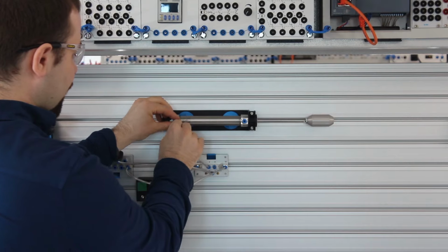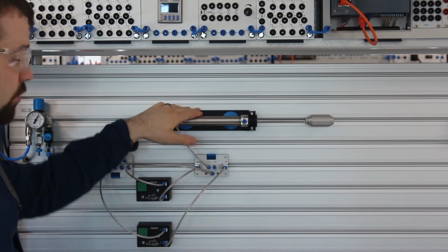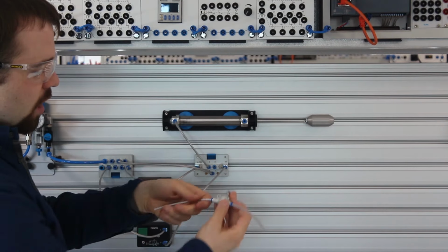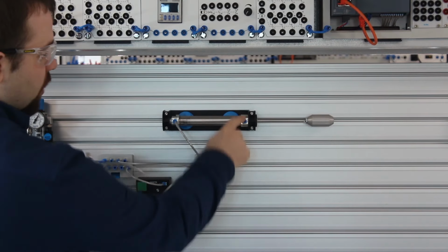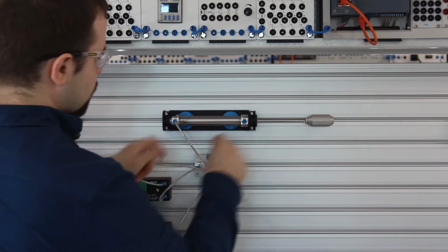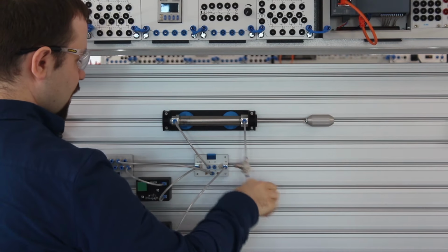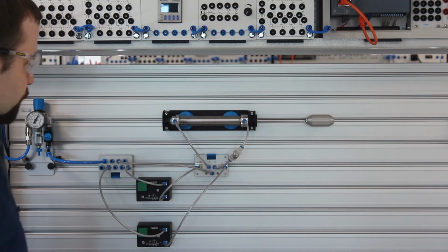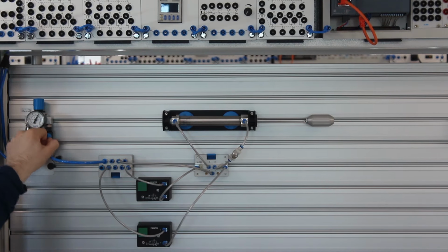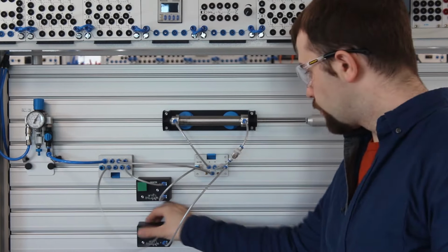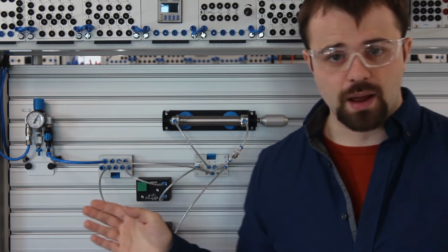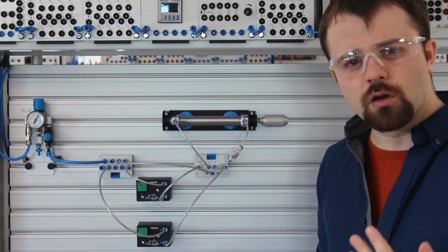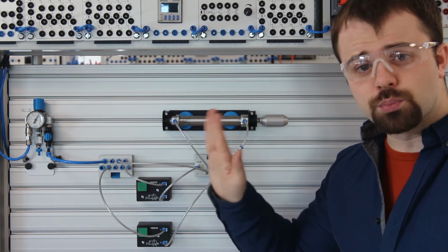So now the air going into the cylinder is restricted. The air coming out from the cylinder, I'm going to exhaust with the arrows pointing away from the cylinder. So we're restricting the air that is exhausting. There we go. Now, when I turn on the air, and let's push it back, so again, it goes back with full speed. Now, when I press this button, it'll still come forward slowly, but you'll notice that I won't be able to spring it.